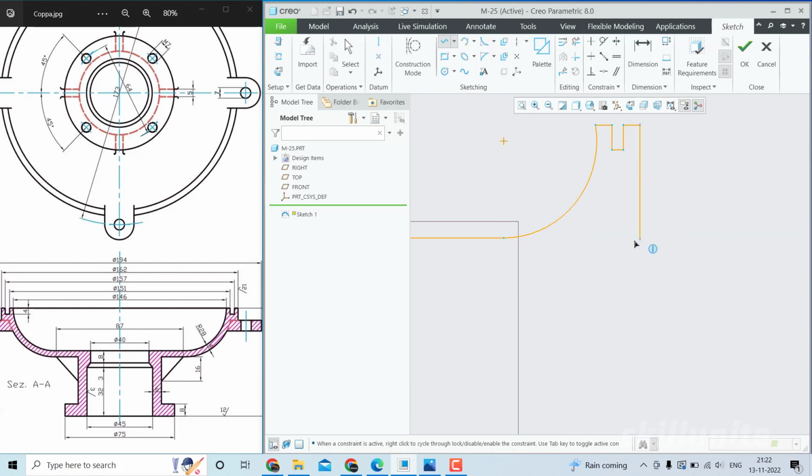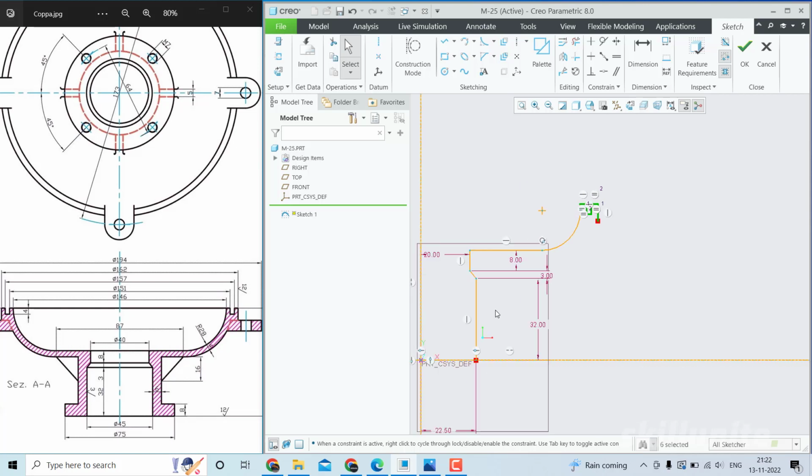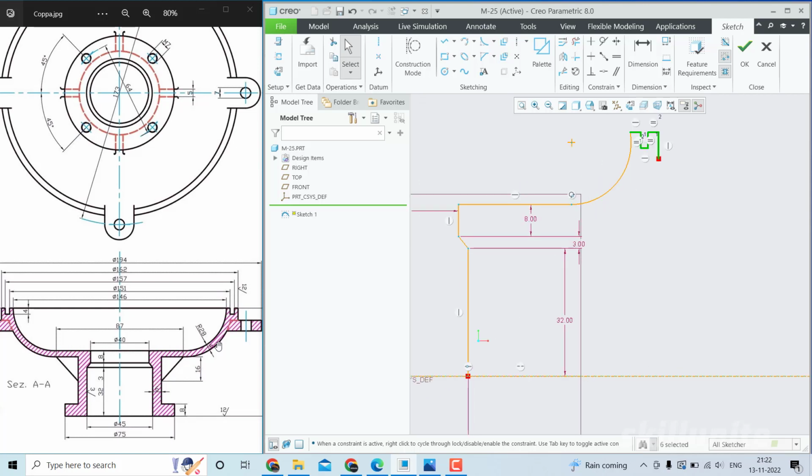So after this, you can make it straight. Instead of creating this, we are just making the object over here and we are going to connect it in this way. So maybe after this we can use just offset over here. As you can notice, it is 4 mm offset. So let us make that. So maybe before going to make this, we will make the other shapes as well. So now you can use offset with the 4 mm.